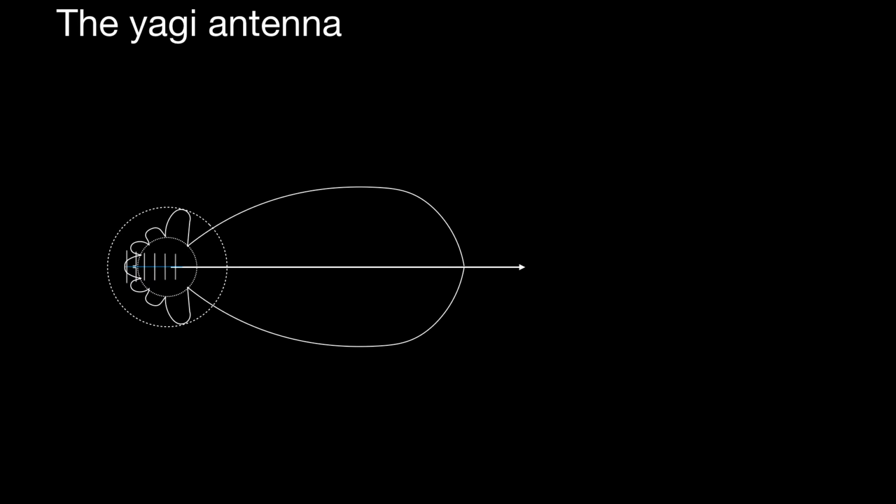In terms of drawing its polar diagram or its radiation pattern, if we place the yagi antenna at the center of our diagram, and then plot on the diagram points of equal field strength. Practically speaking, if we were over a nice flat area, we'd walk around with a field strength meter, plotting on a map points of equal field strength.